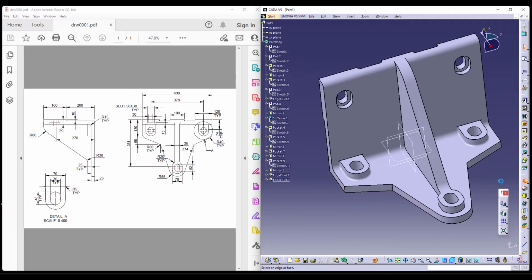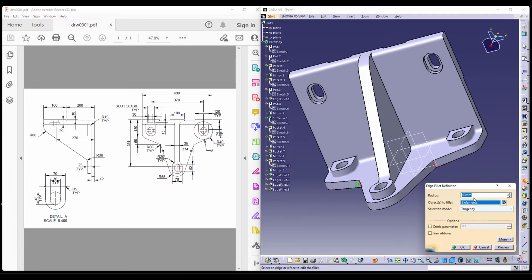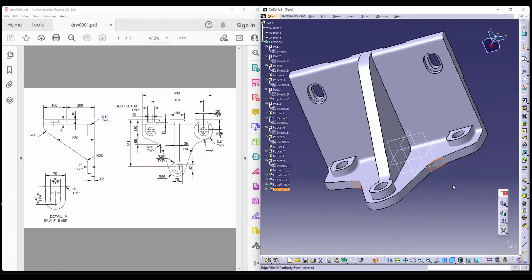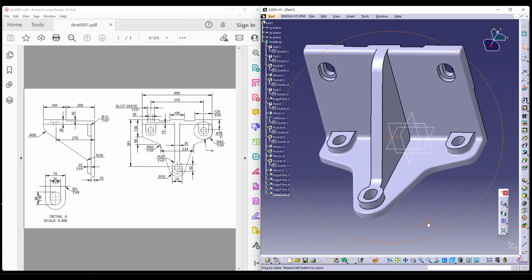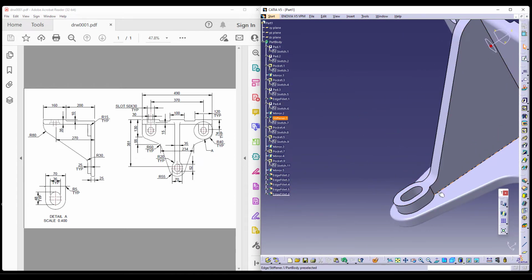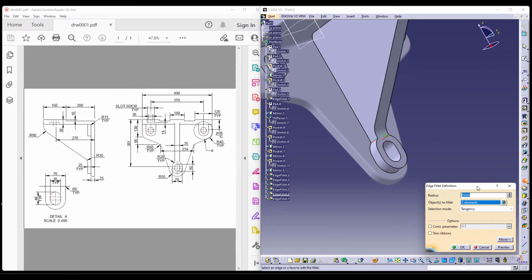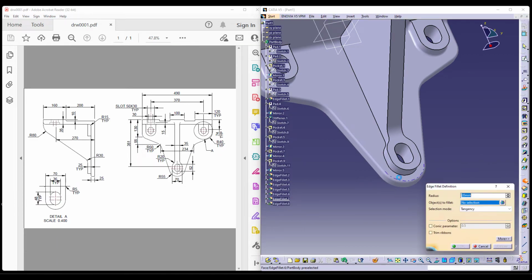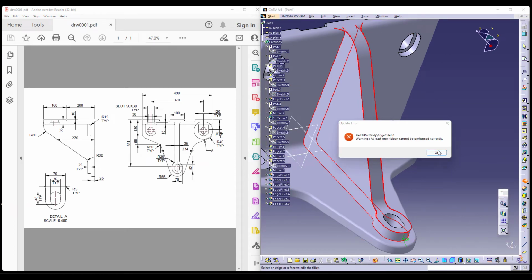Now, we have other fillets as well, that is located at this location. These two are of the same fillet, which is of size 40. Now, there are other fillets as well in between this and this, which are of size 60. Now we can directly give fillets because they flow through the complete model over here as well as over here. This is supposed to be 5. And same way, we also have 20 given over here at this edge. This is 20 as well as this is also 20. So once I give this 20 and give rounds now, it flows through the complete body as you can see. It flows through the complete body to give rounds on the body.